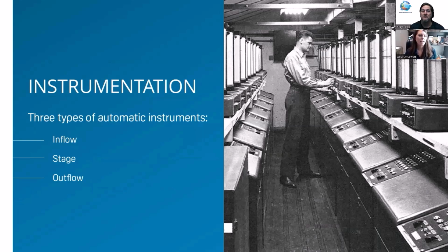So they had inflow controllers that controlled how much water could enter the model at the different tributary and confluence points. They had stage transmitters that were at the same locations as the USGS gauges across the river basin model that had a probe at the bottom that would read the outflow stage. And then they had outflow returns and pulls throughout the system to pull out water to account for any losses that would naturally occur as you work your way downstream, and to handle the final outflow back into the pump and the sump system. And this is what the control house would have looked like.